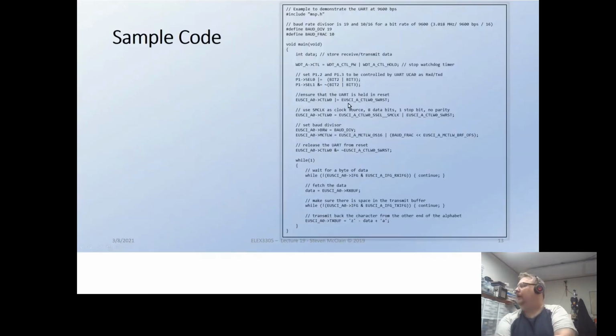Well, code. There's our setting the W. Now here we're just OR-equaling, right? So that's just going to set that one bit. We don't care what the rest is. Here we're doing an equal. Now when you do the equal, you basically are setting all the bits. So if it's a 0, it's a 0. If it's a 1, it's a 1. You're setting everything. So when we do that, we want to make sure we also still have that reset word into the thing we're setting. So keep that bit set so that keeps the clutch in.